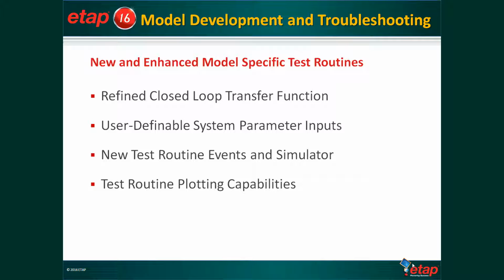At the same time, ETAP 16 UDM in standalone mode received a new simulator which allows us to simulate any kind of transient condition within the system without the need to execute it in the transient stability engine. This gives us a whole new dimension of simulation capabilities because we no longer have to test and simulate the events exclusively through the transient stability engine, which at times could be very time consuming.